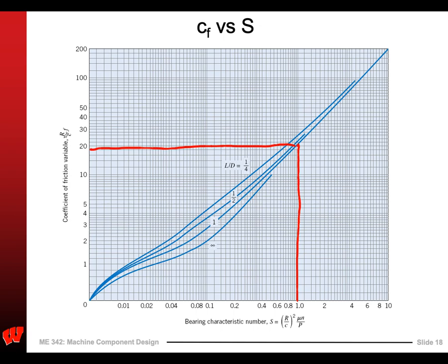Now, this is given as RCF. I'm not sure why the RC is in there because it doesn't make sense that it would show up in two places, but it does. And then I have to divide out the R and the C to just get the friction coefficient between the journal and the shaft, or the housing in that journal. And so you can use Petrov's equation, which gives you a first pass at it, and then you can use the Sommerfeld number and then the friction number to get a more accurate estimate of what the torque losses, the shear, et cetera, is, right?